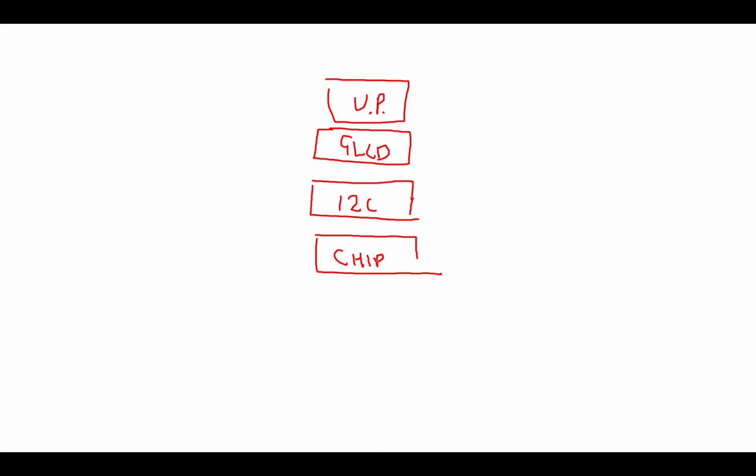So here, the I2C, you can either have hardware, which is what we're just using now. If I change it to software, it'd be no different, by the way. I choose that. I can choose one or the other. In terms of GLCD, there's 34. I think there's 34, maybe 30. We'll say 30 plus, just to be safe. But I'm sure it's a lot more than that. And then up in the user program, you've got lots of commands, lots of primitives, from draw a pixel through to draw a line, different fonts, etc., and different capabilities, triangles, ellipses, etc., etc.